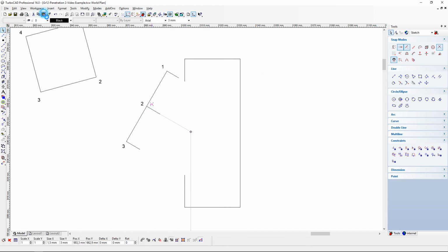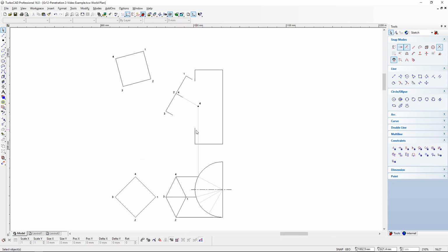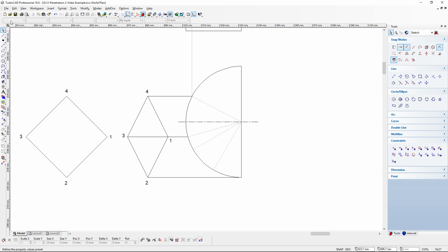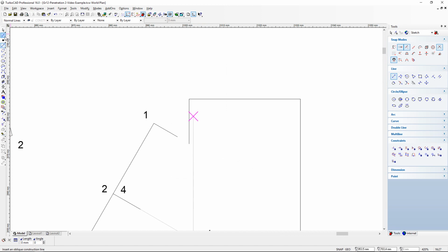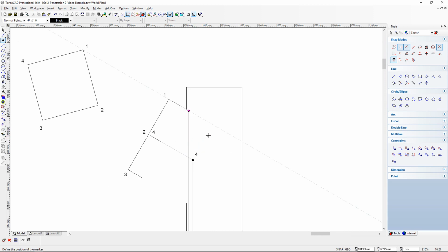I'm just going to label that number 4 so that I know when I use it at a later stage. Now what I need to do is get number 1. So I do the same thing with number 1. I project from number 1 90 degrees straight up, and I take it indefinitely till more or less there. Then again, the same process: use the angle, which is 30 degrees, and project that angle from number 1 onto the projection that came from the top view. And we can now erase the excess and plot a reference point there at number 1.